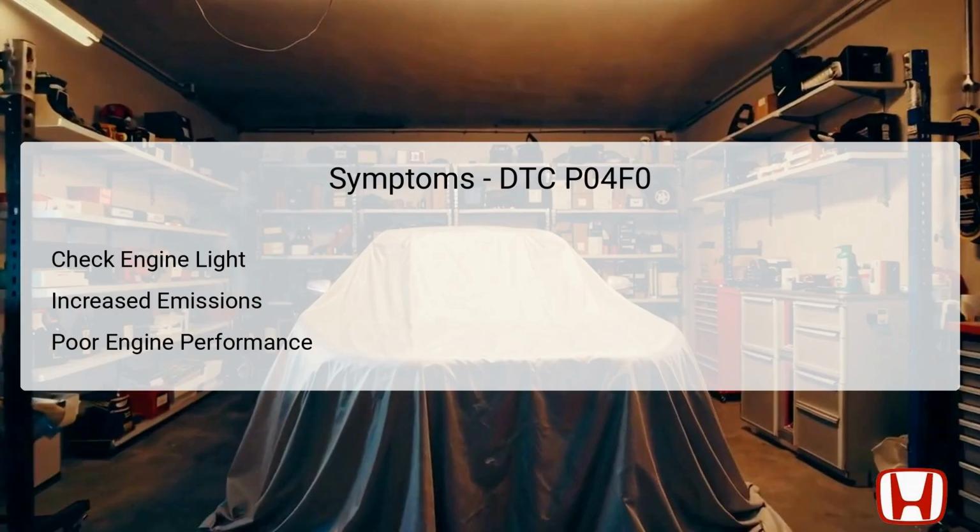Additionally, drivers may experience issues with engine performance, such as hesitation or rough idling, particularly under load. In some cases, there could be a decline in fuel efficiency, attributable to improper vapor management. While these symptoms can indicate various issues, if the DTC P04F0 is present, they should be investigated, focusing on the EVAP system's components and functionality.